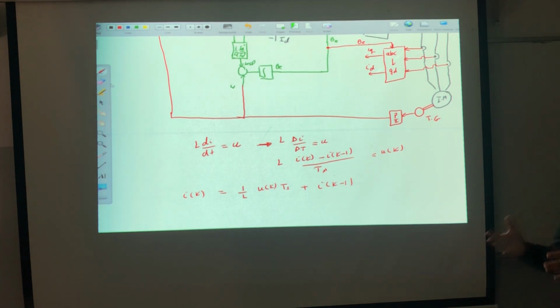Why? The system is non-linear. If I need to judge about the stability, I need to use another technique that is not given to an undergrad in order to deal with it. So in that case, I tell you what, only specify the band according to how much ripple is allowed, and that's it. The second one is what? The PI control plus the pulse modulation. In this case, I need to design. Why? Because the system becomes linear. So I have a method in order to design the system using the linear control theory.